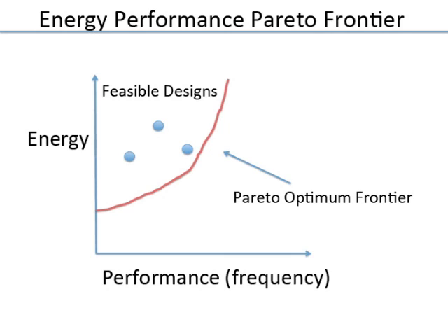Some of these parameters are discrete, like choices for architecture. Either do this or this or this. Do I use distributed arithmetic or do I use multiply accumulate? These are discrete choices. But then you also have continuous choices, that is voltage. What voltage should I use? So no matter what, you have a family of designs. Exploring this space of designs is called design space exploration, and sometimes you have tool support to do it, sometimes you have to do it yourself.